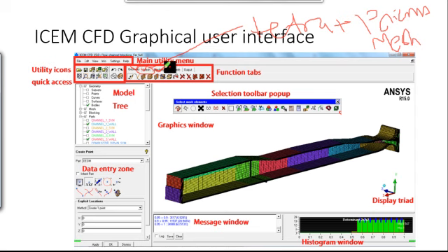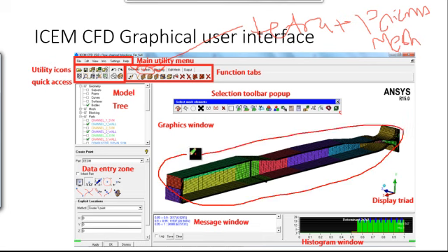So once you get the blocking for that mesh, as you can see over here, this is a full hexa mesh. You need to convert that mesh to the unstructured mesh. Now that will be transformed to the mesh, something like you get from the mesh menu over here. The only difference is that with the help of the mesh tab, you can only get the tetra and prism mesh, but with the help of the blocking, you get the hexa mesh.